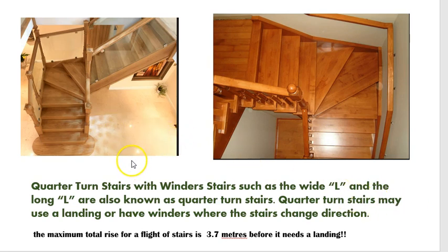And then briefly, we talk about quarter turn stairs with winders. These would be the winders. You've probably all seen these. They did introduce some stricter code requirements for these within the last decade. Basically, because of the danger if you're walking on the inside of the stairs, there's just not enough tread there for a foot to land with this style. This is something you would do if you were tight on space and needed to make that turn rather than just having a landing.